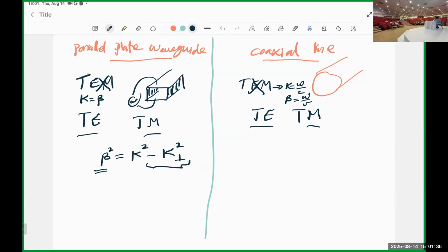Now, if you have a rectangular waveguide, calculating the cutoff wave number is going to be different than calculating it for a circular waveguide. And you have seen this in terms of the Bessel function representation of the fields, and the sinusoidal sine and cosine representation, but always in the direction of propagation, we use an exponential function with a complex exponent.